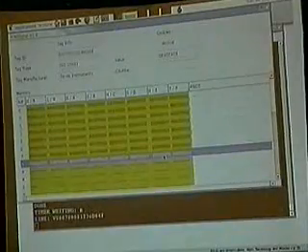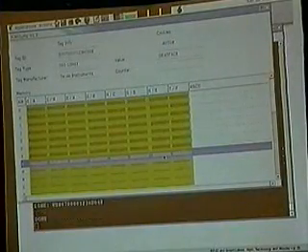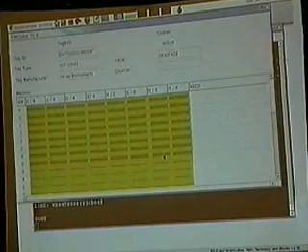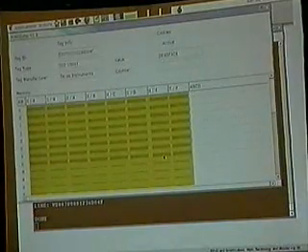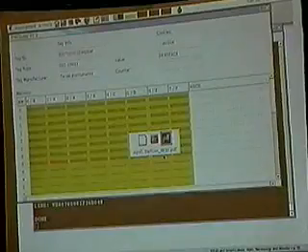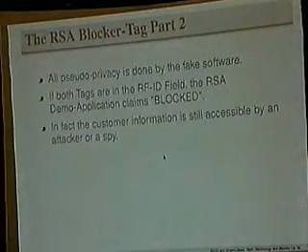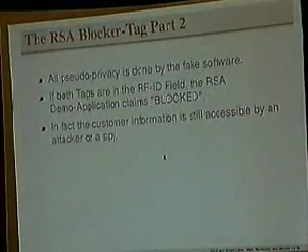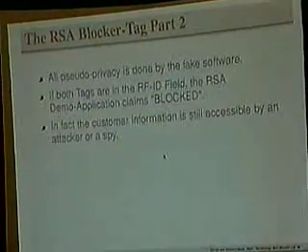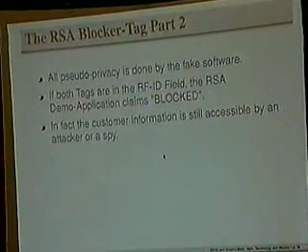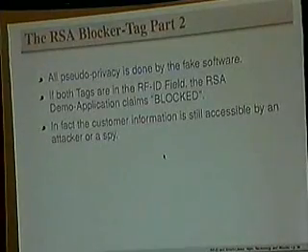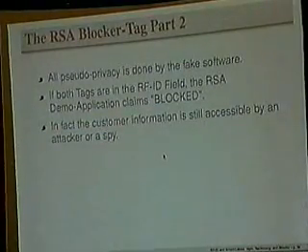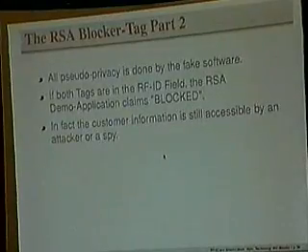Each tag has a unique identifier called UID. This UID is needed for the complete anti-collision algorithm. So if you have more than one tag directly in a field, like a big box with 2,000 retail packages, you have 2,000 tags in the field. So you need a mechanism for anti-collision to get each tag separately. This UID is programmed directly at the factory and can't be changed.